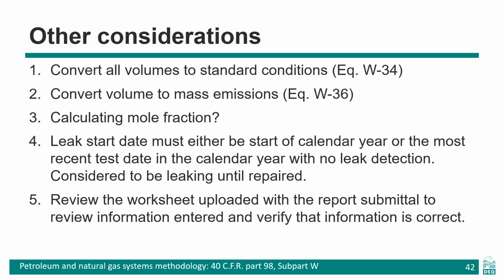Lastly, ensure that the reported leak time follows the regulation. If survey records can't show that a component was not leaking since the start of the year, then the leak must be assumed to go all the way back to January 1st. For identified leaks, check the maintenance logs for the repair date and time and make sure that it was properly tested to show the leak was fixed.